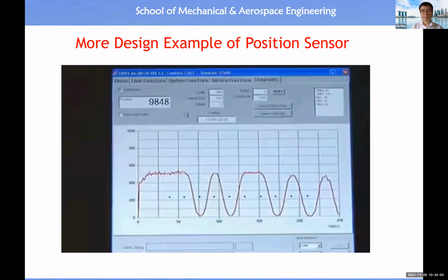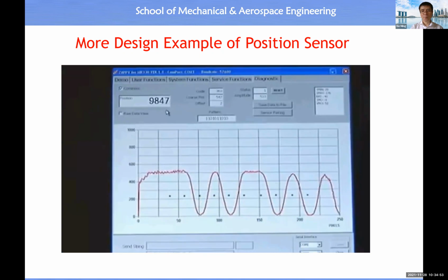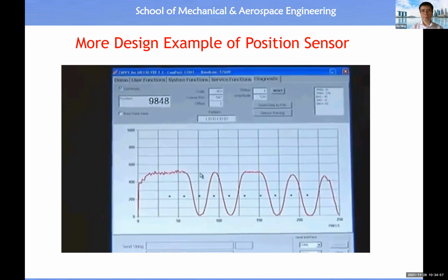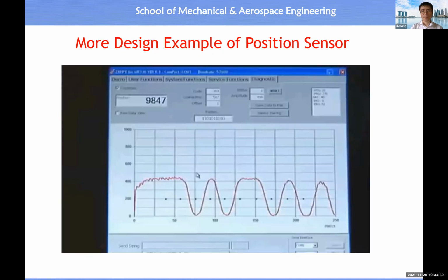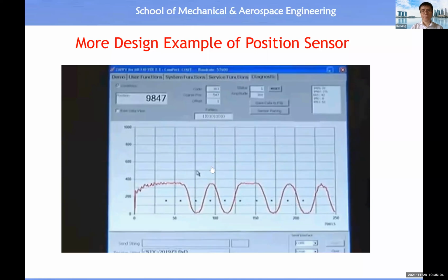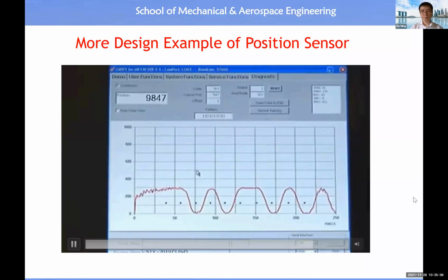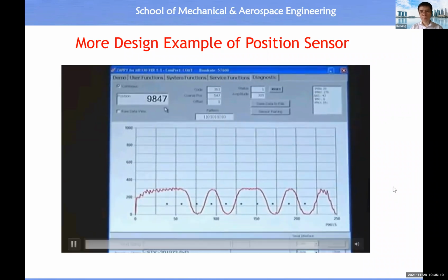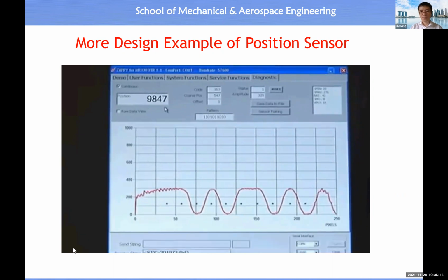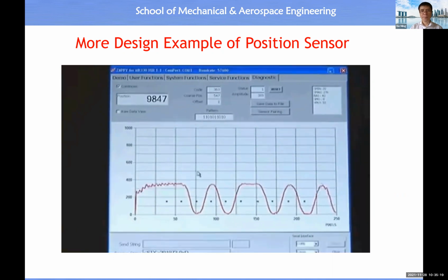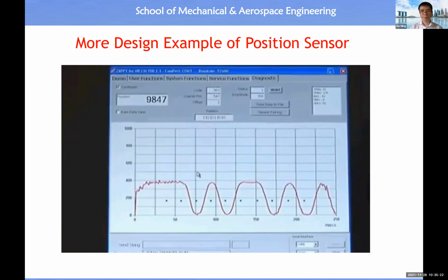This wave graph shows the reading of the sensor. When the optical power changes, as simulated here by adjusting the connector, one can see a drop in the readout waveform. However, the position reading is not affected at all. Rather than using light intensity, Micronor ingeniously utilizes the light spectrum as an information carrier, making this a very robust position sensor. Again, note that the position readout does not change when the light amplitude is brought back to the previous level.